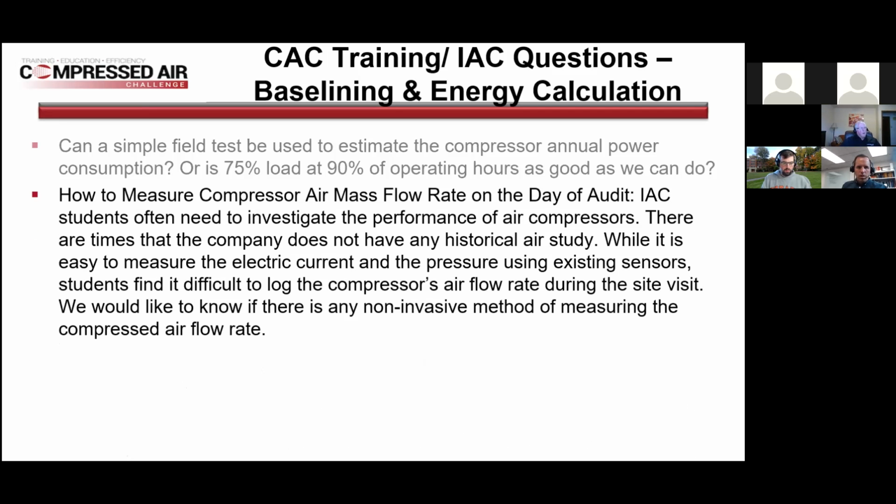So how to measure mass flow on a day of the audit? Often you're looking at the performance. You want to go through and understand. They don't have a historical. And this was going through and asking about logging and being able to do non-invasive. The hot wire anemometer type insertion is probably still going to be your best bet, as long as it's temperature compensating. That does require a hot tap and putting it in.